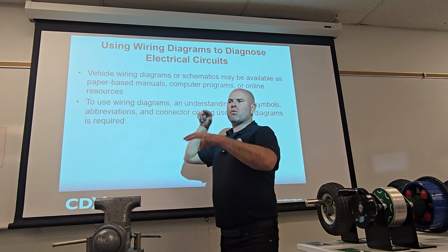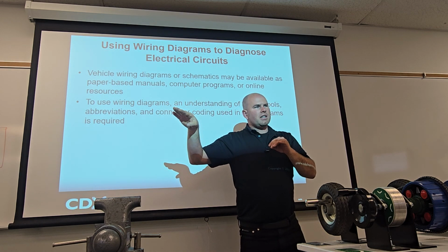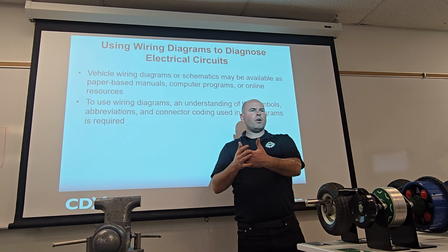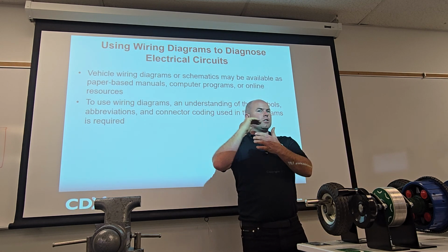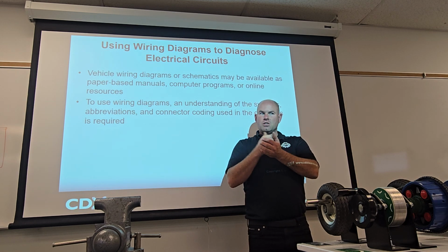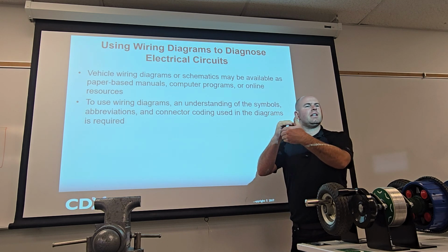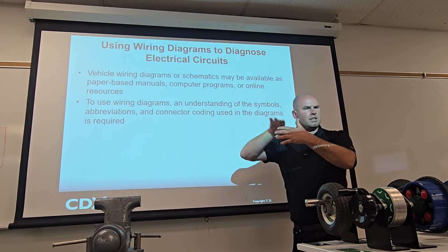So what if I were to probe the wire that's giving the voltage to the LED and put it on my meter, and it shows 12 volts, but then it were to flicker, and when it flickered, it still showed 12 volts. That tells me what's wrong. Did you pick that up? Exactly. If the 12 volts is steady, but the flickering is occurring, it's inside the light.